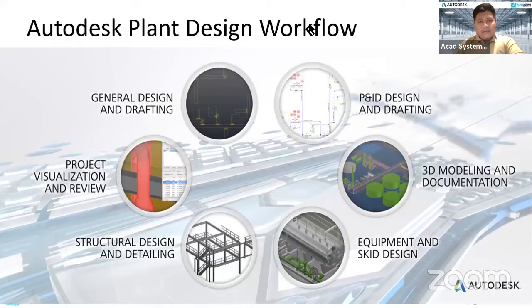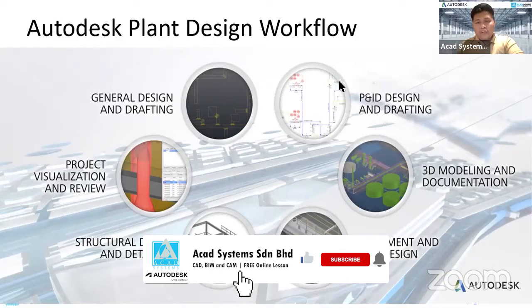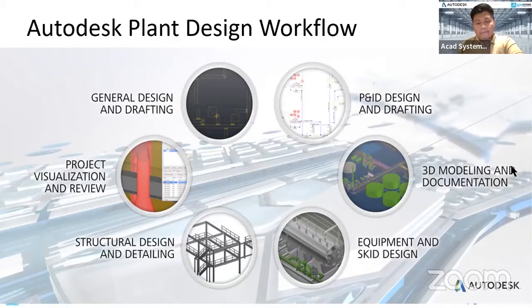Autodesk Plant design workflow. The general design and drafting are normally created using AutoCAD 2D. After you're done with the general design, you can go to the P&ID. This P&ID needs Plant 3D. Then the 3D modeling and documentation. This 3D modeling can also create a GA design, GA drawing. Then equipment and skirt, structural and detailing, project visualization and review, and that will be the most common workflow.